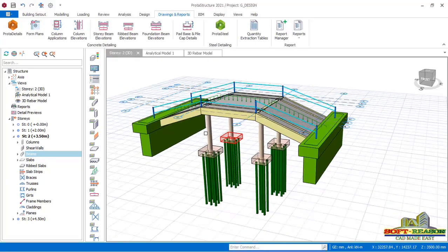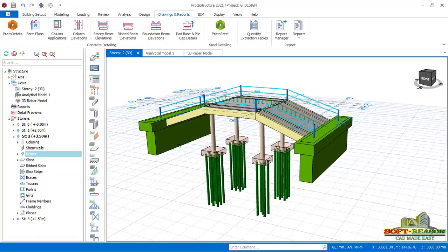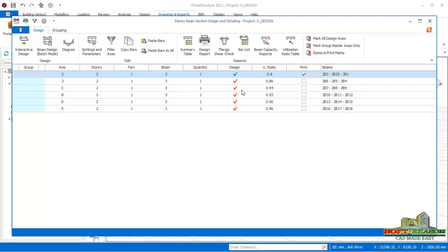Quickly, we failed to look at the beams. So let us quickly look at the beams. All right, so if I click on this beam, right click, and then click on the RC design right there, you will have this. Whenever you're having your design check showing good but in a red color, it means the design is not valid. You have to make it valid. It's only this first one that is valid. This one is not valid.